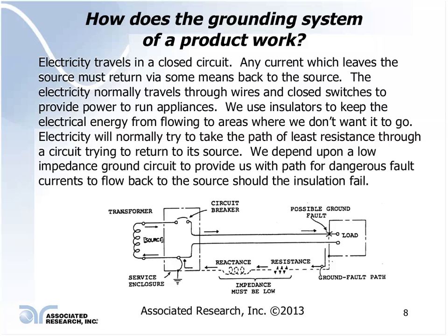Over here on this side, we have our power distribution transformer. It shows the secondary coil of a transformer, which feeds into a circuit breaker in the cabinet. Coming out of the circuit breaker, this is our hot conductor going into our product that is going to be connected to this outlet, or to this line to run our product.